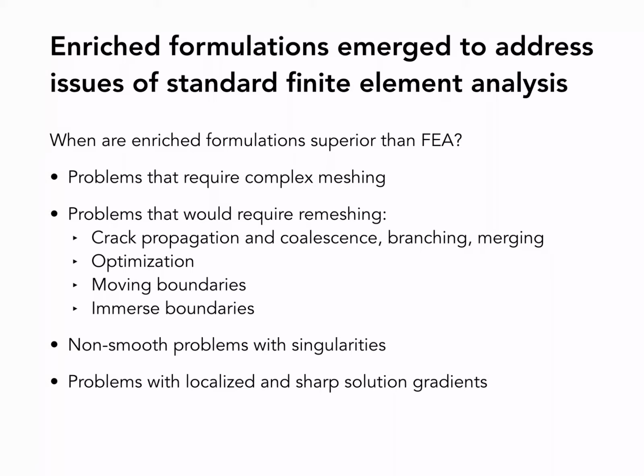And so this course can also show you how to enrich or augment the standard finite element space with functions that you can actually use to improve the finite element solution to those problems. And then again, problems with localized and sharp solution gradients. So if the exact solution of your problem has a sharp gradient inside an element, for example, then you know already intuitively that you have to take these elements around the gradient and refine there, right? But if you can actually augment the standard finite element space with a function that has this sharp gradient built in, then you can also improve the approximated solution. Okay, so let's see some problems.